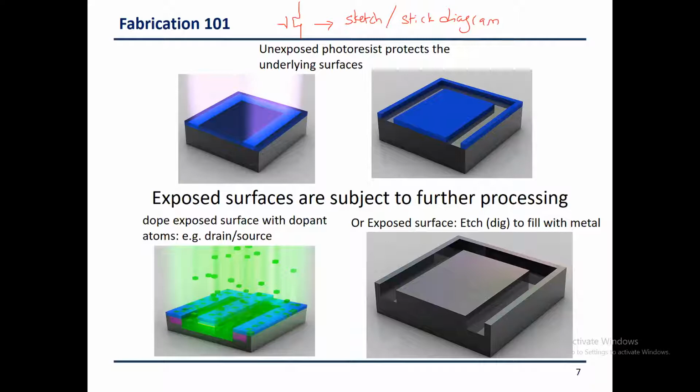Then we will go to the layout, which is really how the different layers, what different layers will be involved, and what are the different dimensions and stuff like that. So this is a geometrical interpretation of the design. Okay, this geometrical interpretation of the design will then be transferred to the maps or the masks. Okay, and this will then be printed on the chip and we will realize them.